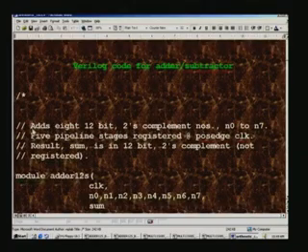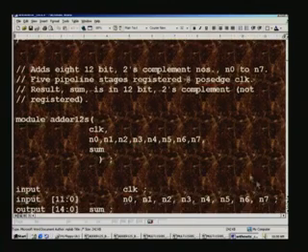So I will add 8 12-bit 2's complement numbers n0 to n7. There are 5 pipeline stages registered at positive edge clock. The result sum is in 12-bit 2's complement, not registered. There is a mistake here. Sum must be 15 bits.